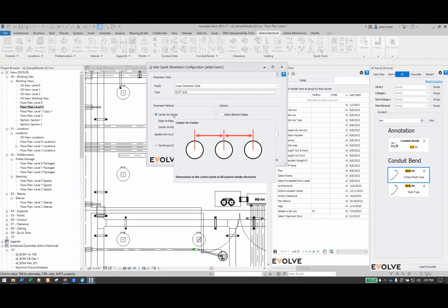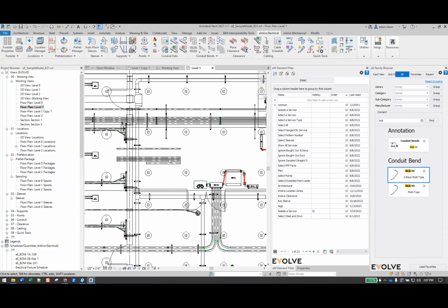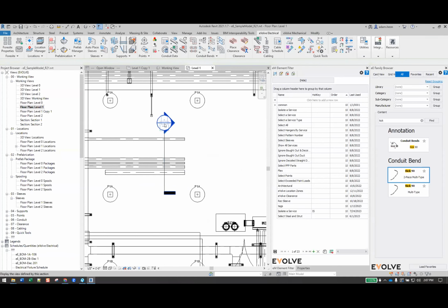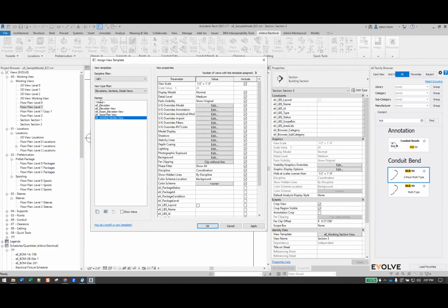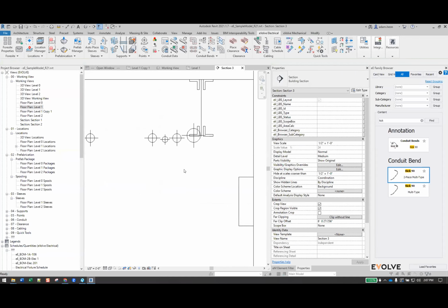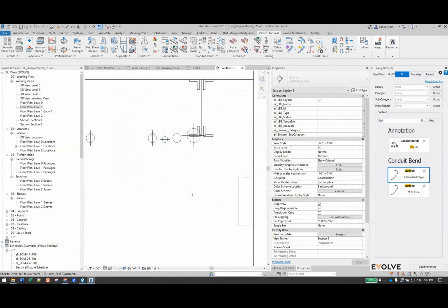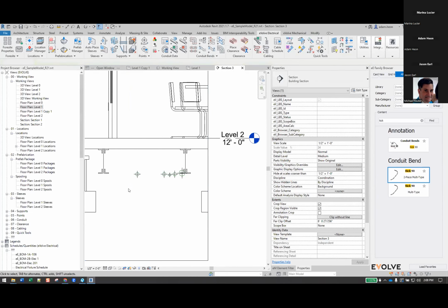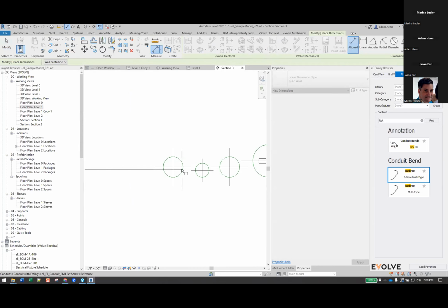On the center to center, something to keep in mind, standard Revit visibility graphics apply to this. So you start a section view of some conduits. If that section view has your rise and drop turned on, just think of native Revit. If I want to dimension to the edge of this conduit, there's no snapping to the edge of it.